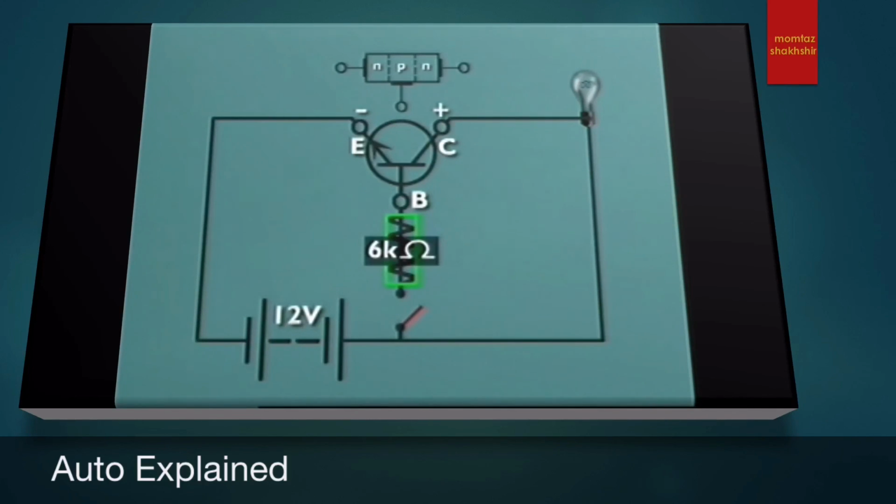If the control switch is open, the depletion layer at one PN junction is blocking current from flowing through the transistor and driving the load. With a closed control switch, a small current flows through the emitter base PN junction. The base has only a limited number of charge carriers, so extra ones flow across the emitter collector PN junction, letting current operate the load. The transistor then operates as a low-resistance conductor. A small current through the base lets larger current flow across the emitter-collector junction. The transistor is then said to be turned on.